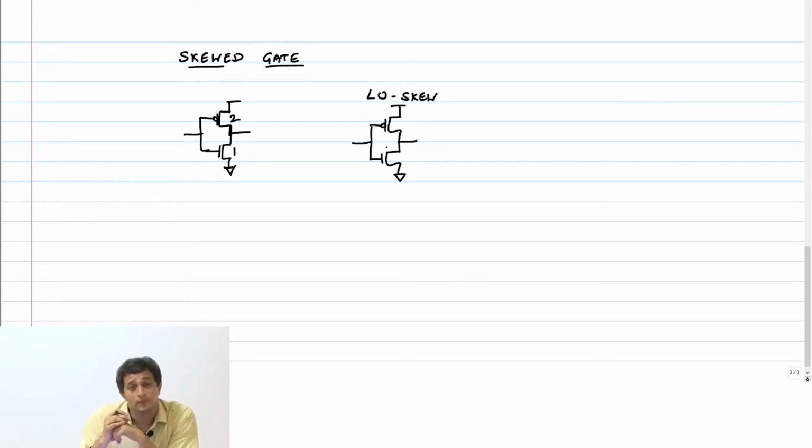Increase the size. Okay, so you're saying instead of 1 and 2, you want me to make this, let's say, 2. But if I make it 2, what's going to happen to the logical effort? It will not decrease, because remember, logical effort doesn't depend on whether it's 1 or 2, because I'm going to compare it now to a reference static CMOS inverter with the same drive strength.